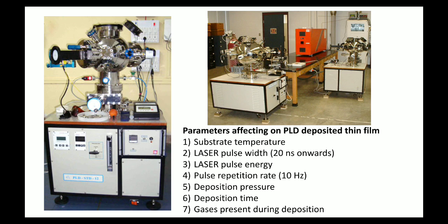Then the deposition time. If you increase the number of pulses, then it will take longer for deposition. If you decrease the number of pulses, then it will take less time for the deposition.